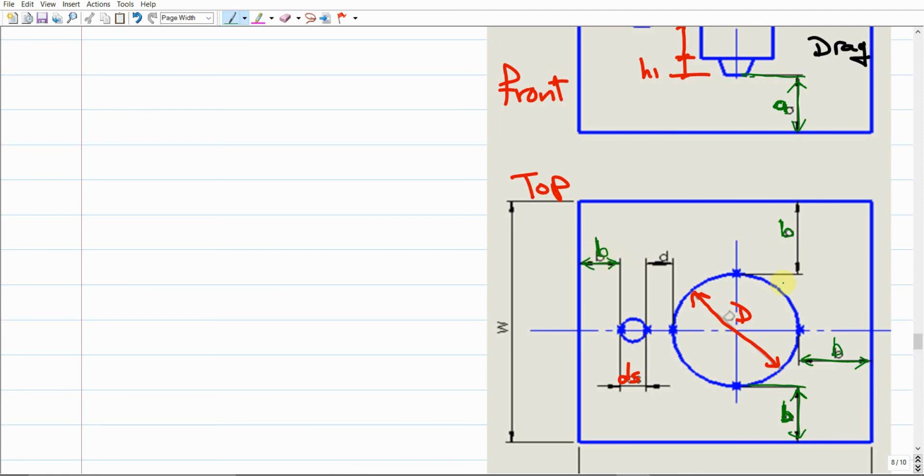How much is B? We're gonna find it from a table. But as you can see, there should be a small part of sand located between the bottom of the down sprue, or the lower part of the down sprue, and the casting itself. This dimension should be D. How much is D? We're gonna find it from the table. So this arrangement of the dimensions is fixed.